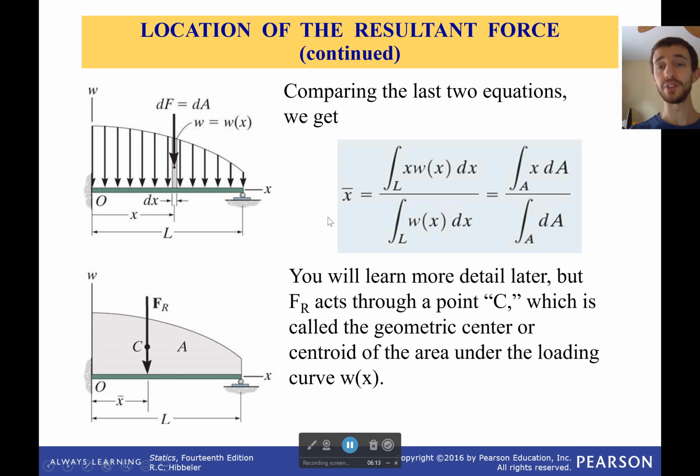So finally, in the end, when you solve this right here, and be careful that dA does not cancel just because it's on both sides, then you will find the centroid. That's the distance from the origin to our point where this force would be applied.